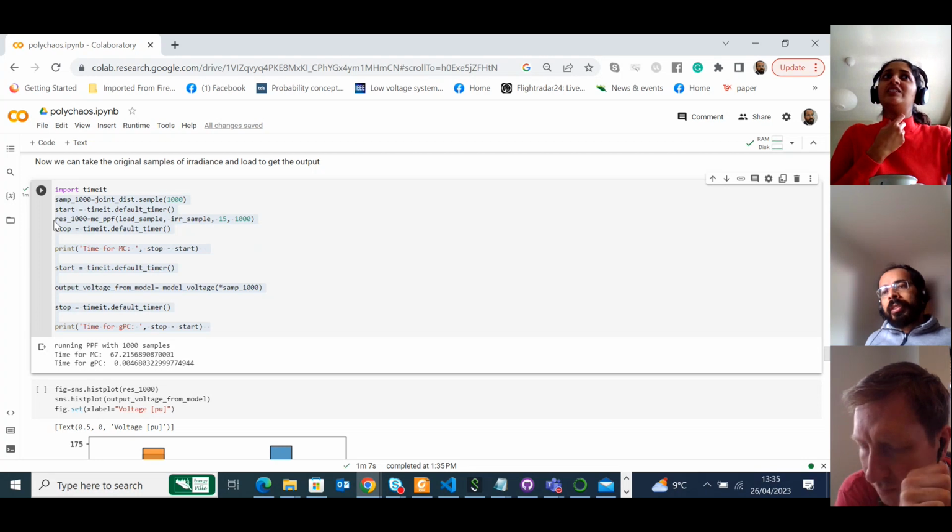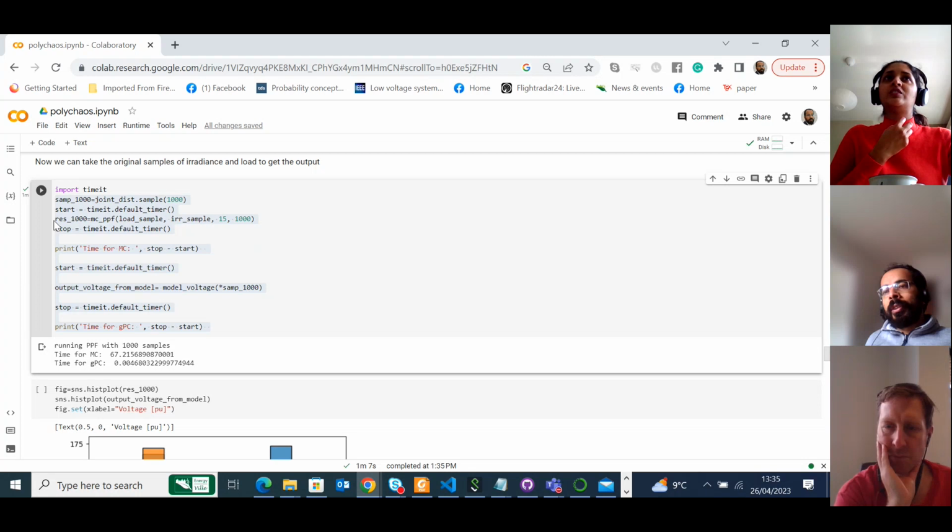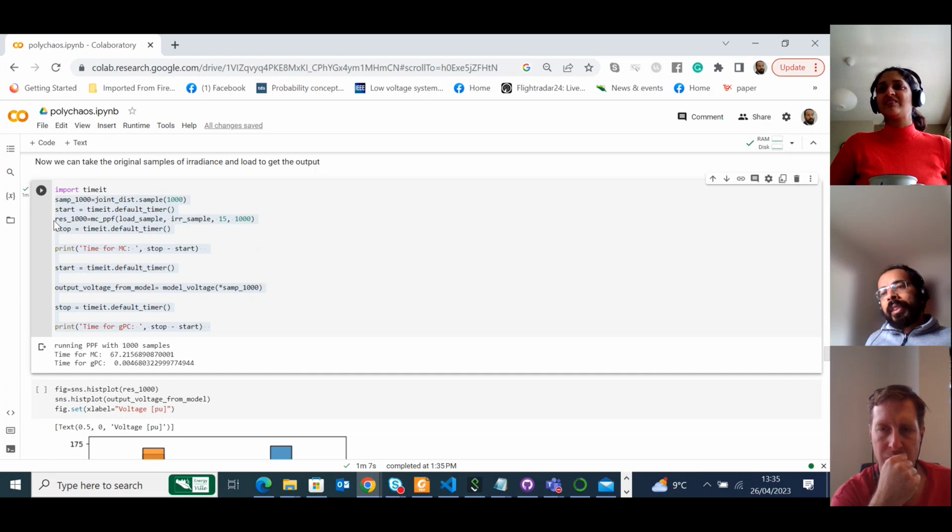So if you repeat your simulation, you'll get the same output again and again. If you do a simulation with 100 Monte Carlo samples, you have seen before, once you get 12% probability and another time you get 15% probability. So if you don't take sufficient samples, you might get different results every time. But with a Sobol sequence, you get the same result every time.